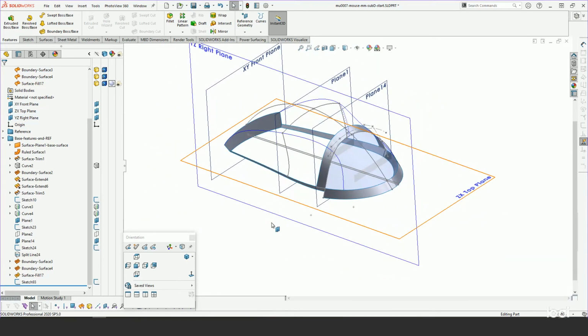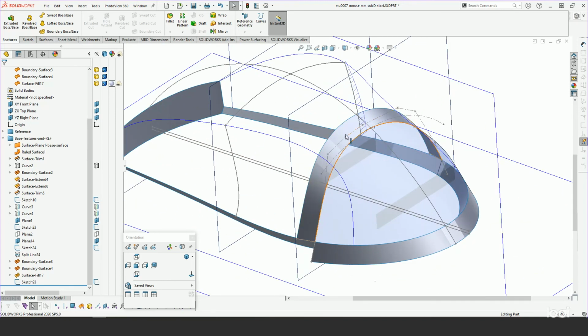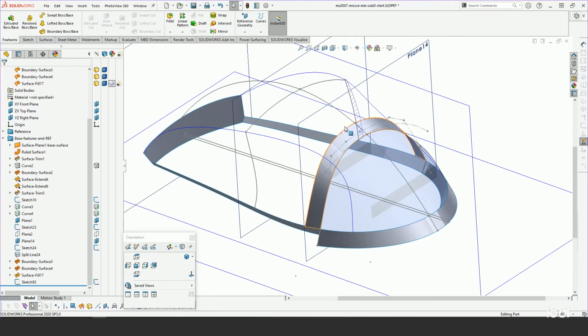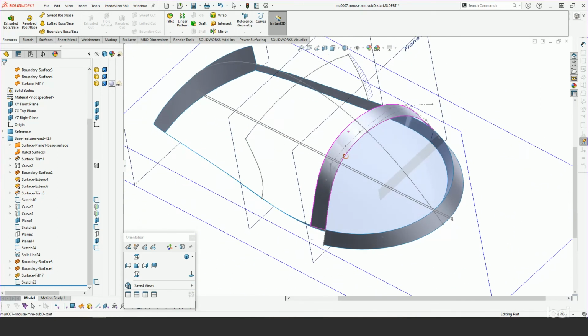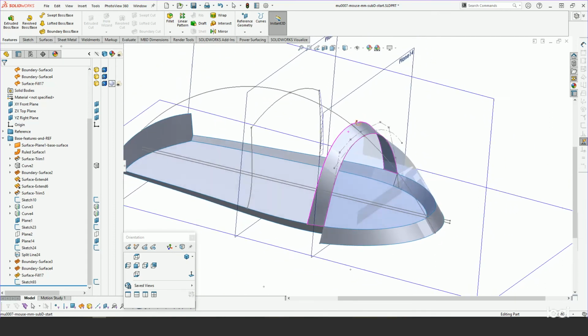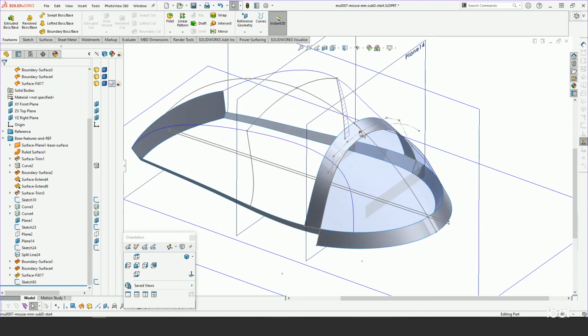And I call it hybrid because we are using a hybrid approach of surface and solid modeling to get to the final goal. And it really speeds up the process because, as I say, there's certain things that sub-D is not very good at, and that is doing swept surfaces, organic planar surfaces, and just primitive shapes. And I'm using all these to my advantage to help that sub-D be successful.